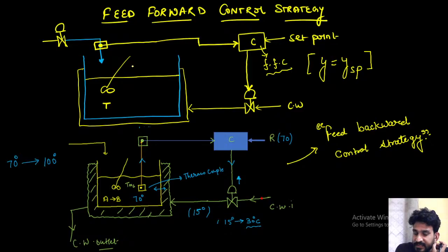The controller takes action to prevent the disturbance. It is taking the signal from the disturbance, and if the controller finds any variation or misbehavior of this input stream, then it will already have taken the action so that my system remains at the steady state. So this controller is rejecting the disturbance.